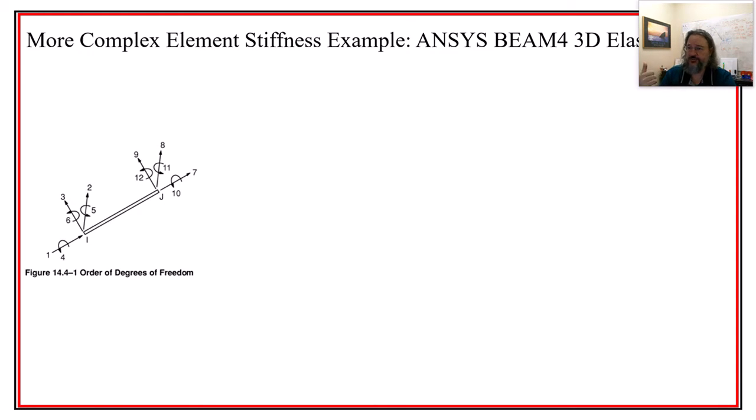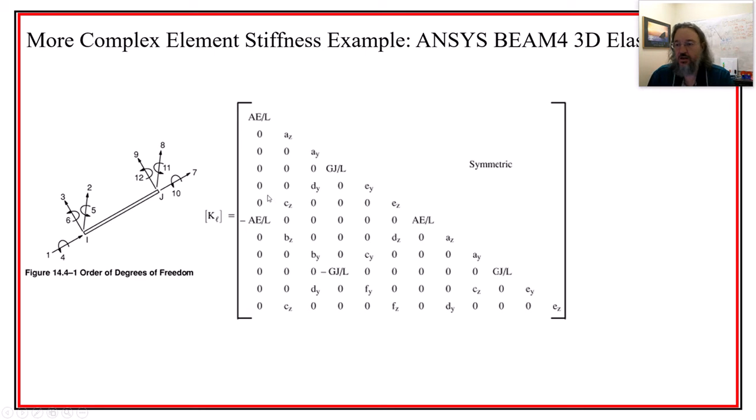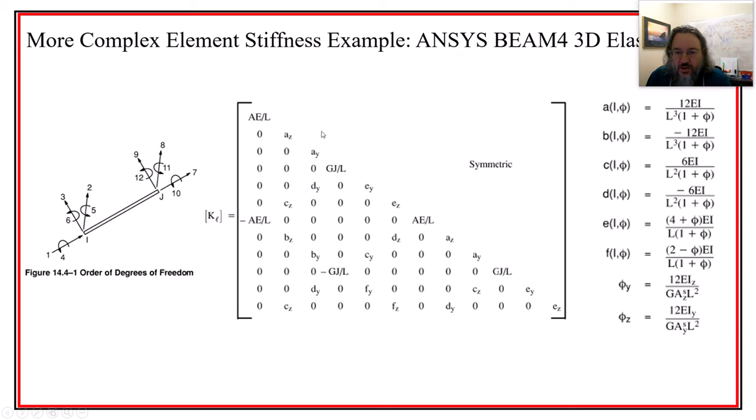There's axial, there's left and right, and there's up and down, right? So there's just X, Y, and Z. So it can translate in any of the 3 directions, but it can also rotate, right? Because it has bending. So it's got an angular degree of freedom at each one. So this is a 12 degree of freedom element. Just one element has 12 degrees of freedom, and you can see there's a lot of zeros inside here.